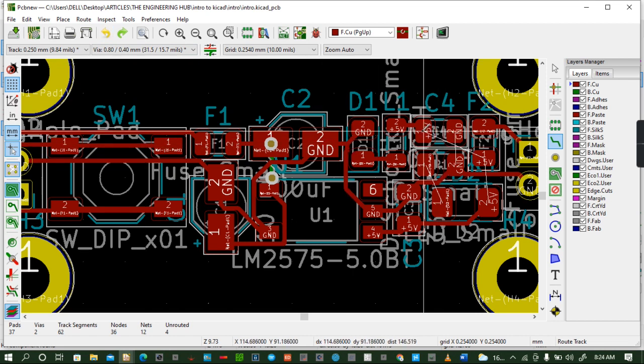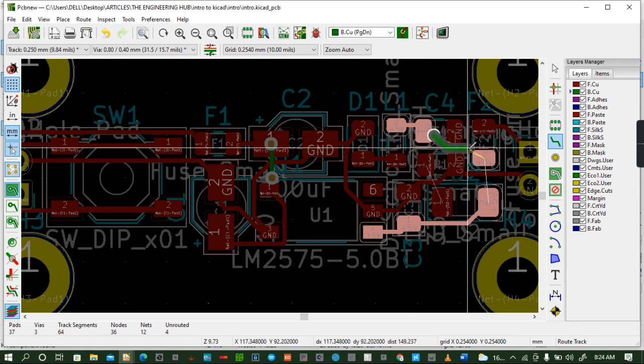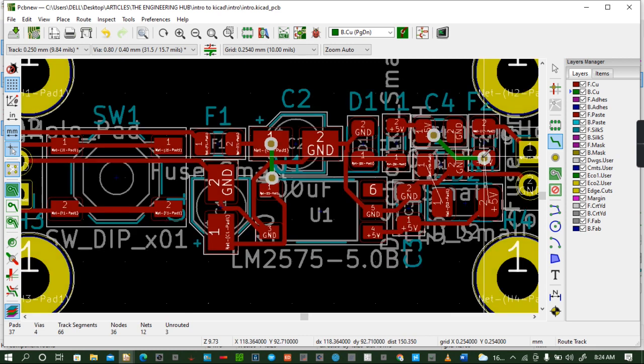So you come and hit here, then you hit V. You place the V there, then you proceed to this other edge, and you hit V for via. The component is connected. So this is the point for via, add via. But when you're doing the traces, you do it automatically by hitting V, which is a shortcut, and you connect the two components using a via.